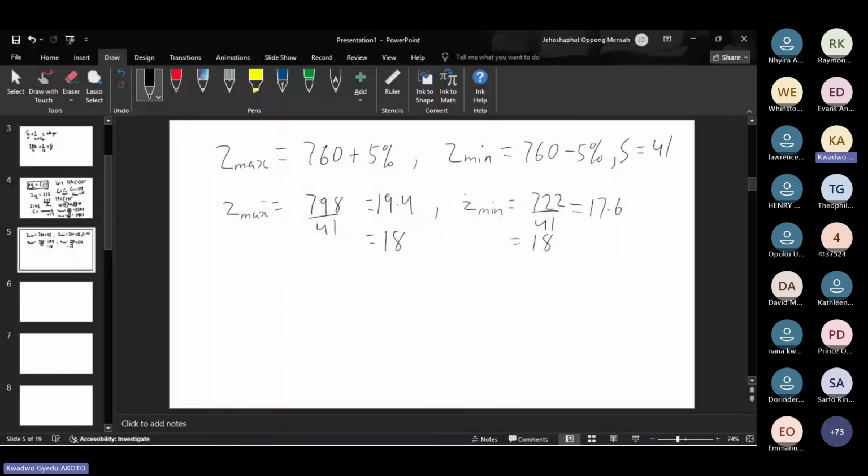All right. For our question B, it says, for the number of slots chosen in part C, so we are still keeping our number of slots to be 41, right? Determine A, the number of coils per slot. We had U max to be 3, and U minimum to be 3 when we choose our number of slots to be 41.